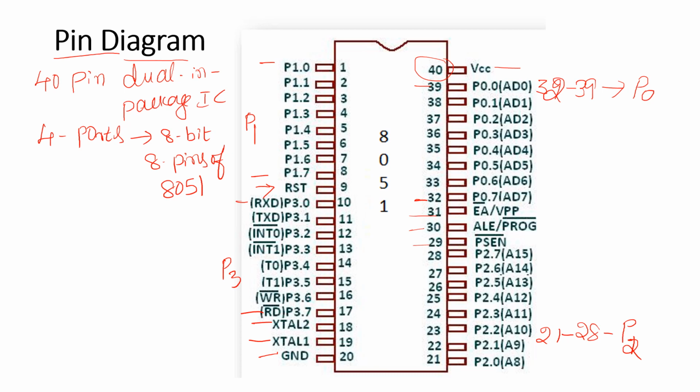Now, the port pins of P3 are multi-functional. We can make use of them either for input-output operations or for additional special purpose operations. Port 0 and port 2 pins are considered for input-output operations, and can also be used for address and data transfer to the external memories.